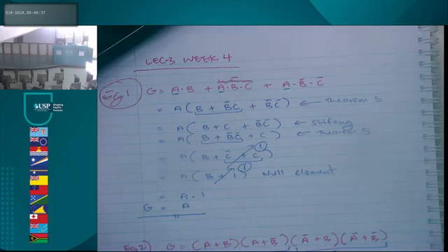Okay, some people say 4, but in reality, if you take into account that there's a NOT here, there's a NOT here, there's a NOT here, right? So it might end up being 3 AND gates, 1 OR gate, and 3 NOT gates, right?